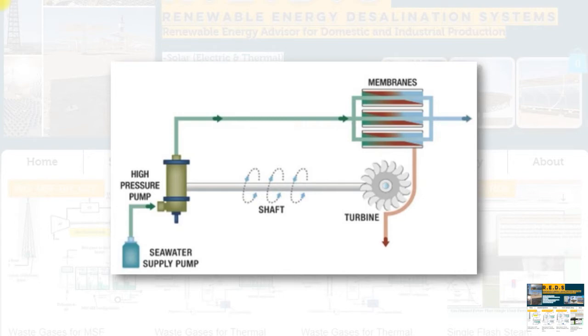We have here, of course, the brine, as we saw from the past slide, that is rejected. The pressure here is nearly the same as the pressure of the high pressure pump. So we have to utilize and harvest such a gain from this brine as much as we can.